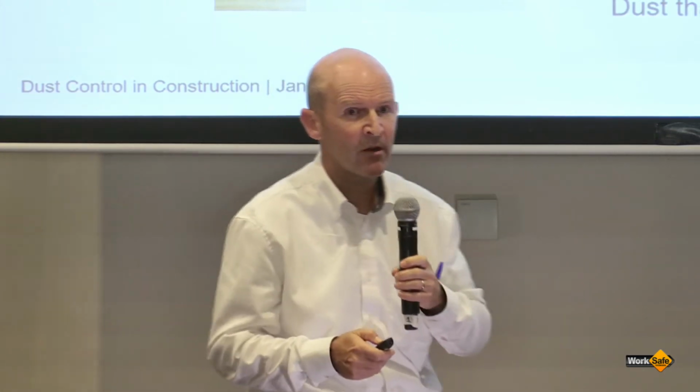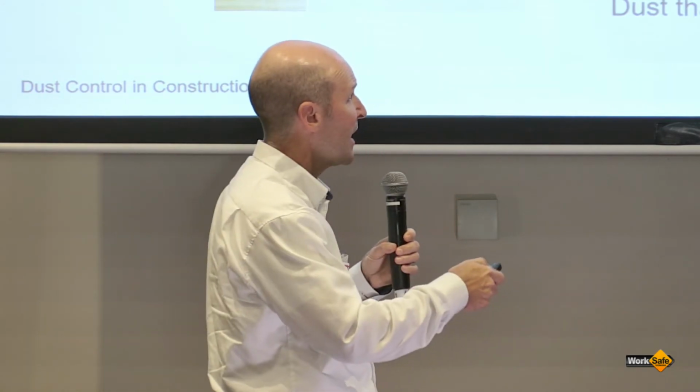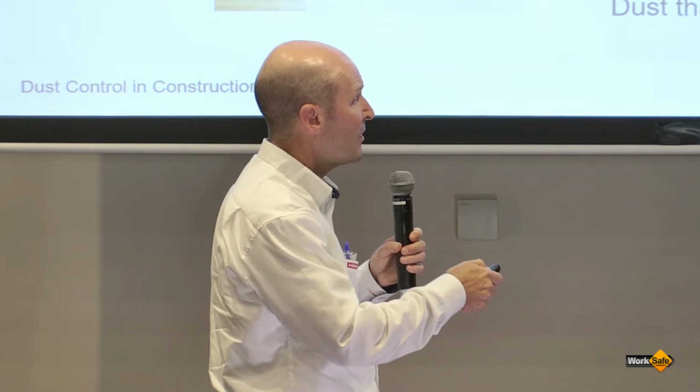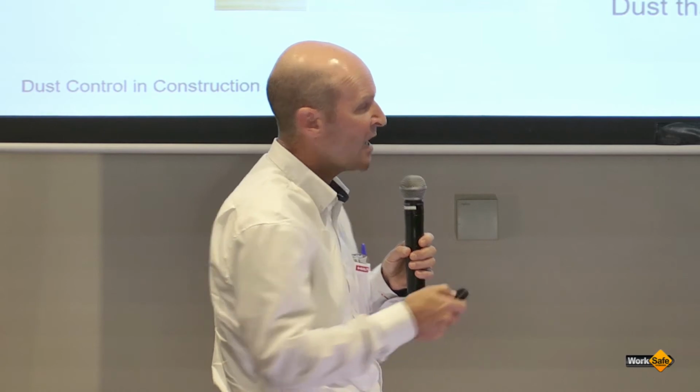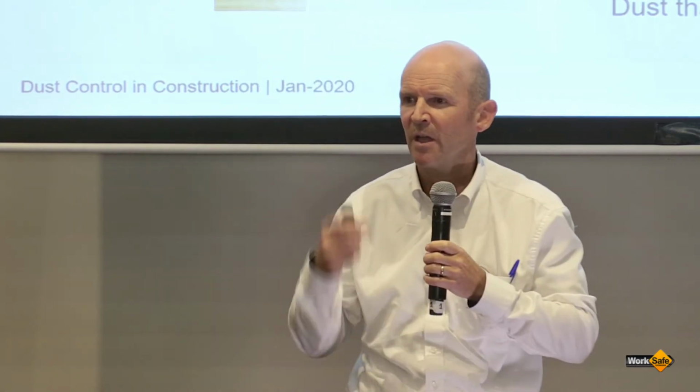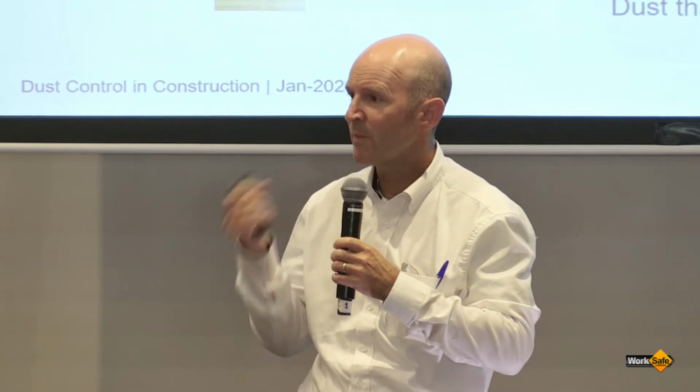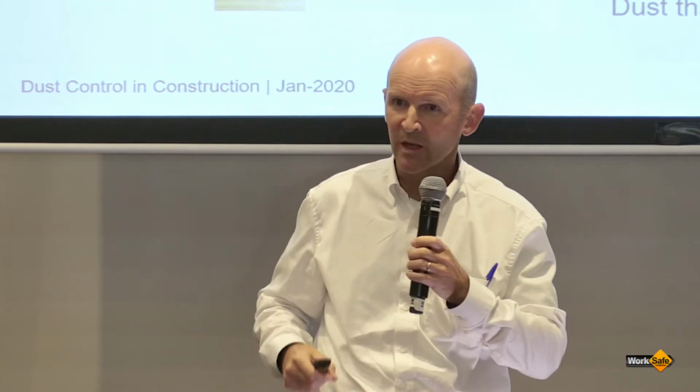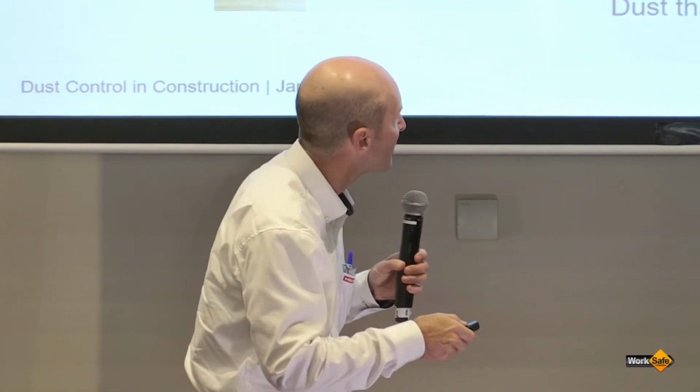Another key thing to point out is this aerodynamic effect. Now, if I dropped a 10 micron silica particle, and a 10 micron silica particle is in that respirable range, so that can go deep into your lungs, if I dropped it here, 1 meter above the ground, it would take 5 minutes to settle.